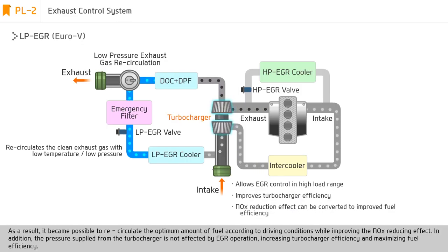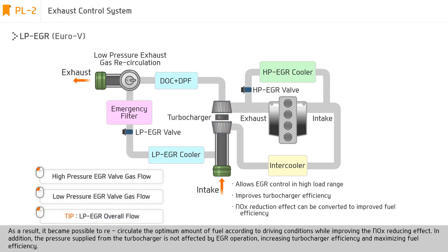As a result, it became possible to recirculate the optimum amount of fuel according to driving conditions while improving the NOx-reducing effect. In addition, the pressure supplied from the turbocharger is not affected by EGR operation, increasing turbocharger efficiency and maximizing fuel efficiency.